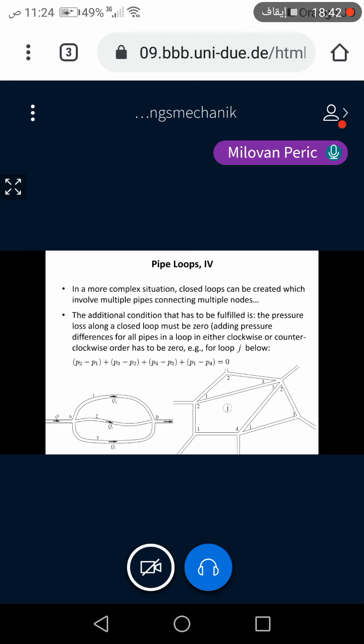And if there are any losses of fluid along these pipes, because very often small, let's say, individual gas consumers in a city gas network, these branches will not be taken into account. There is simply an assumption that there is a certain number of connections, and they will be distributed like a continuous loss along the pipe. But this also needs to be taken into account.